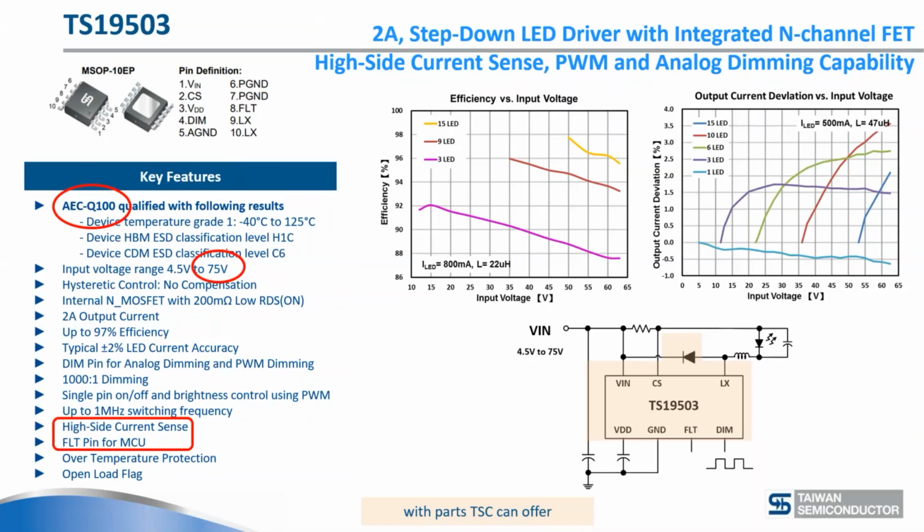The switching frequency is 1 megahertz, and actually what is then typically automotive or the high current sense is used also in automotive is, of course, there's a fault pin that actually the device not only measures the typical fault conditions, which is also including faulty LEDs in the circuits, but it also has a pin to actually give feedback to the controller that does it.